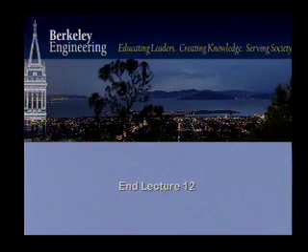They had velocity saturation 0.3 for the N and 0.6 for the P, right? Yeah, I think so. If you think about it in terms of critical field, the critical field, which means the field at which the velocity, the mobility is degraded to half, is about 5 volt per micron. Okay. So 5 volt per micron means on a 0.1 micron device, half a volt. So now what we are looking at in this case would be 3 volts per micron.